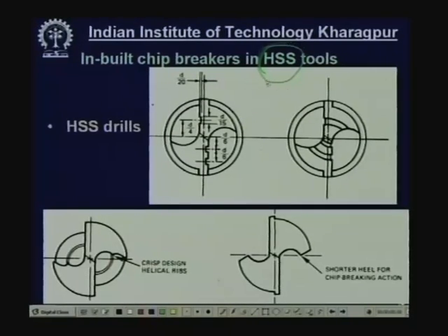Because of these unique properties, these are still used in industry along with other modern cutting tools, but not everywhere. These are used for some cutting tools which have very difficult geometry or configuration like drills, milling cutters, hobs, gear shaping cutters, form tools, taps and dies and so on.